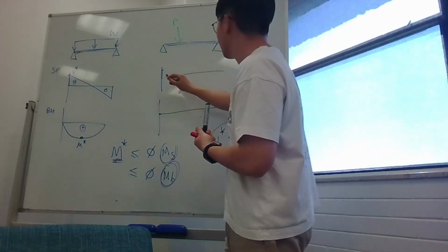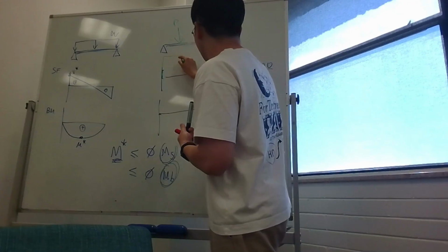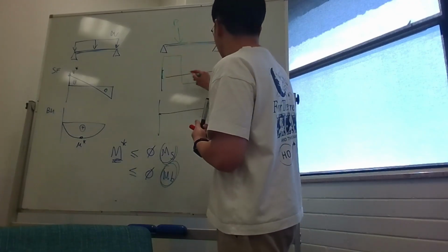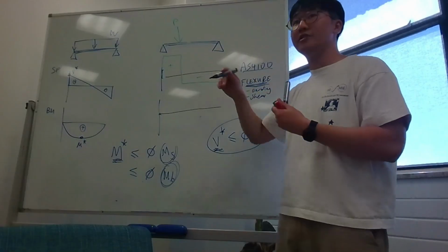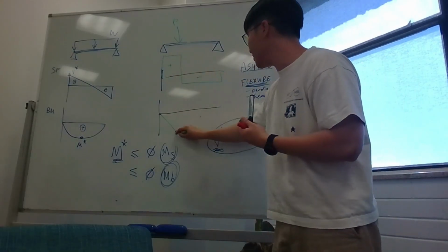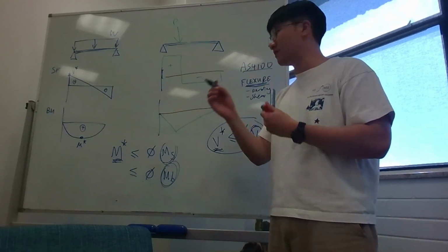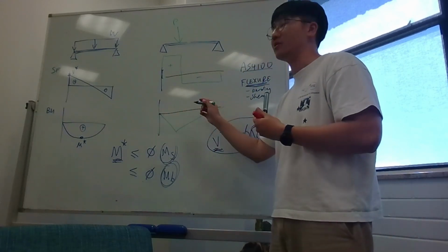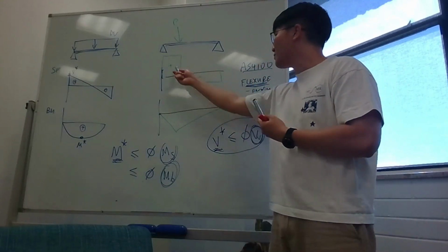Okay, so shear force, instead of being even, ends up doing this. The left block and the right block, in terms of their area, have to be equal. This is in order for the bending moment to end up being 0 in the end, right? So you go up to some max and you drop back down to 0. So area 1 has to equal area 2, right? But what has happened to our shear force?